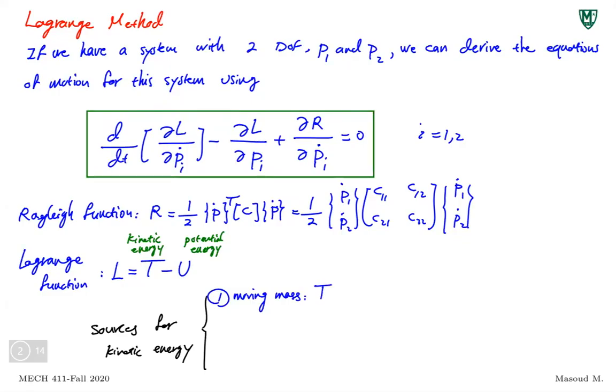We said the kinetic energy for that, let's say T translation, because basically it's a translational motion, is equal to 1/2 m x dot squared, or it's better to say v squared, velocity. We've seen it in dynamics, and we talked about it when we talked about the energy method. So it's basically a translational system: 1/2 m v squared. The second type would be a rotating mass.